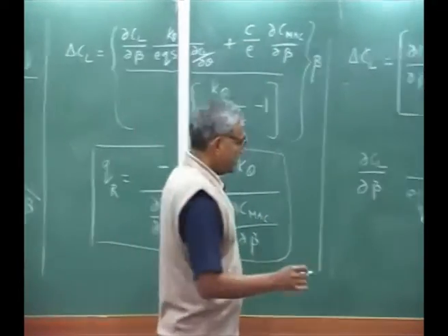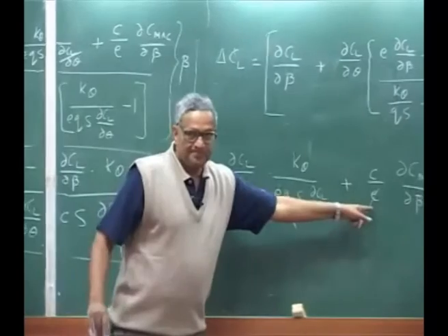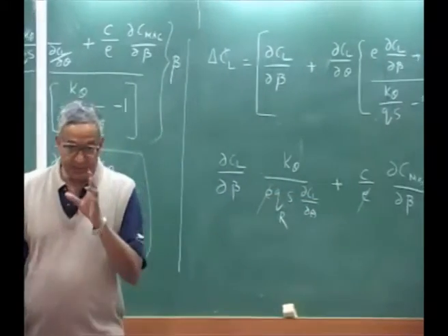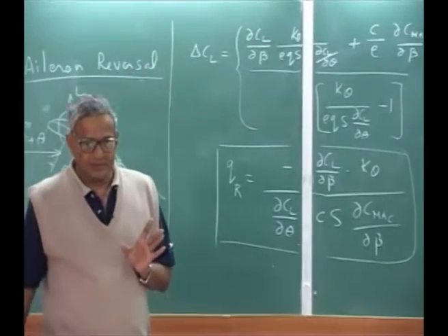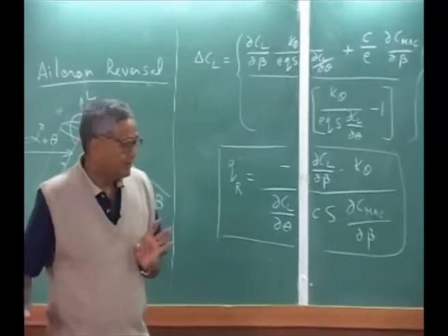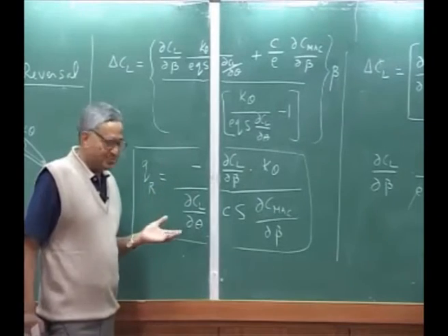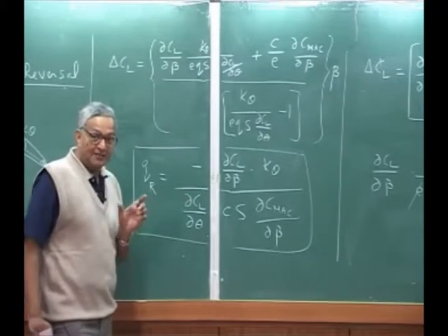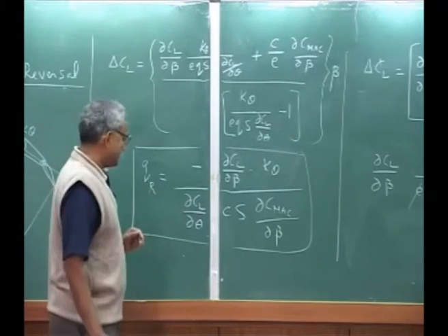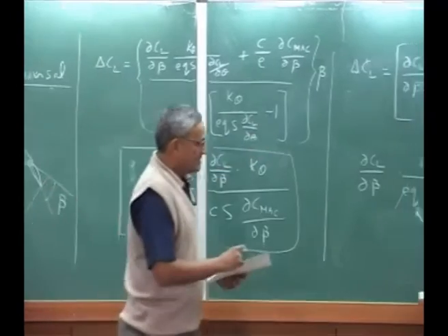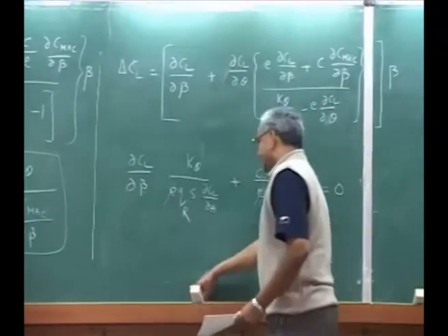And please understand, E cancels out. So the interesting thing which comes out of this is the offset has no meaning. In the sense, it doesn't matter. Your control reversal speed or aileron reversal speed is independent of the offset between the elastic axis and the aerodynamic center. Right here, that is why I wanted to put it in one place.